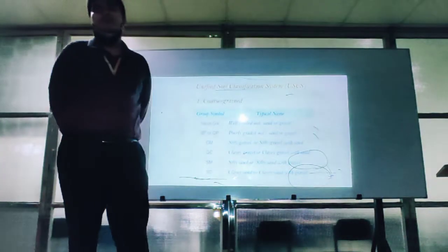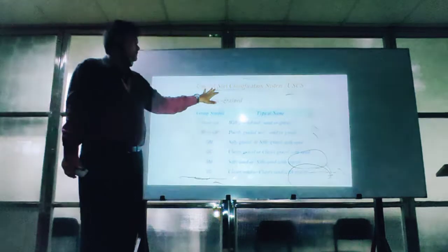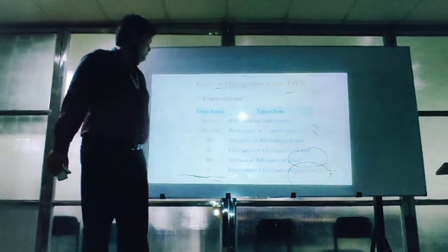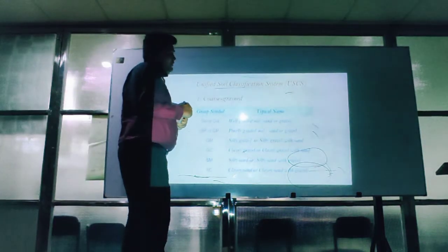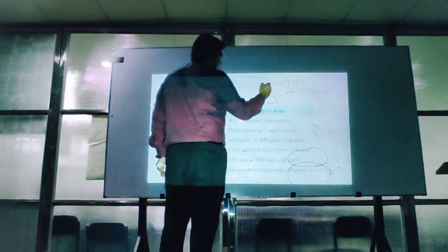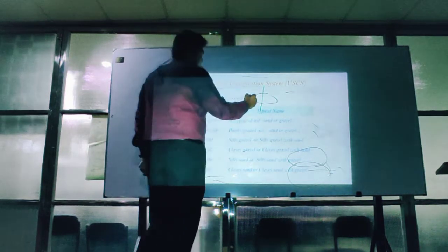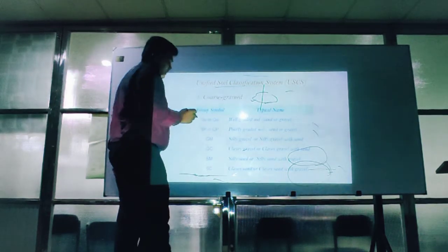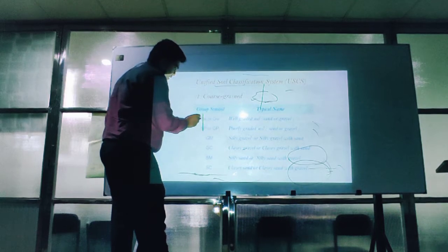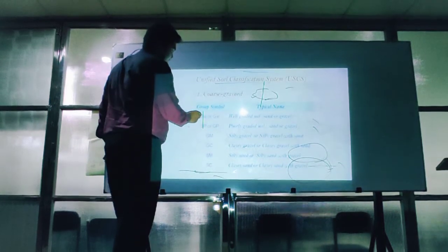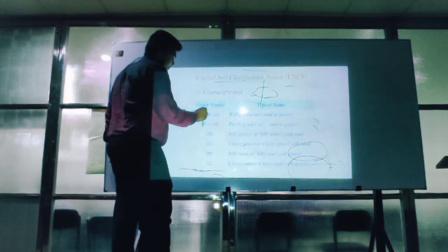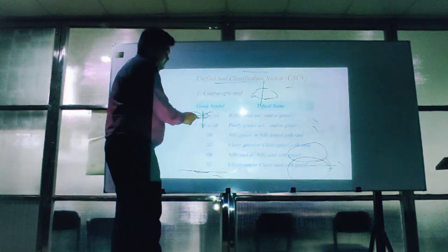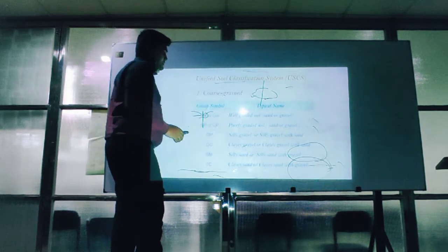Today our discussion topic is the unified soil classification system, and I am going to present coarse-grained soil. First of all, there are some symbols for coarse-grained soil. Basically, we divide the soil into two parts: one is the gravel part and another is the fine or sand part. There are some group symbols here. The left letter is the particle name and the right letter is the gradation or plasticity. That means S is sand and W is well graded.